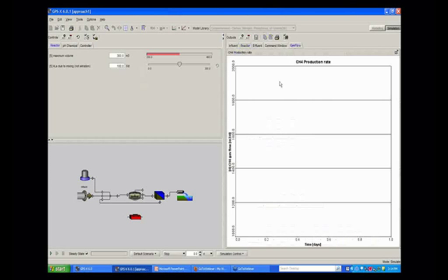So we're going to go to the analyze mode. As soon as we go to the analyze mode, you can see this changes from 200 to 400, which is the reactor size I'm going to analyze. And we are going to see that if we run the steady state simulations, the reactor size is going to change, and at each reactor size, we are going to see what is the CH4 production rate. So I'm going to run this analysis.